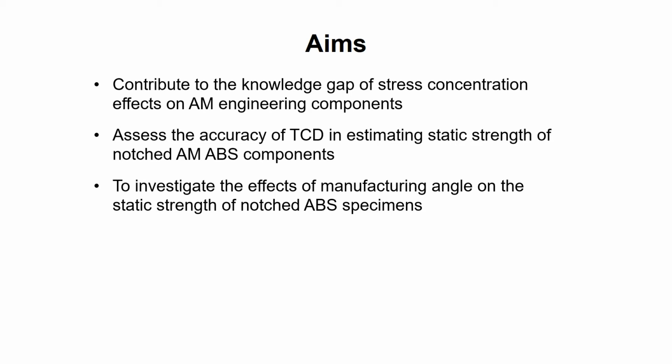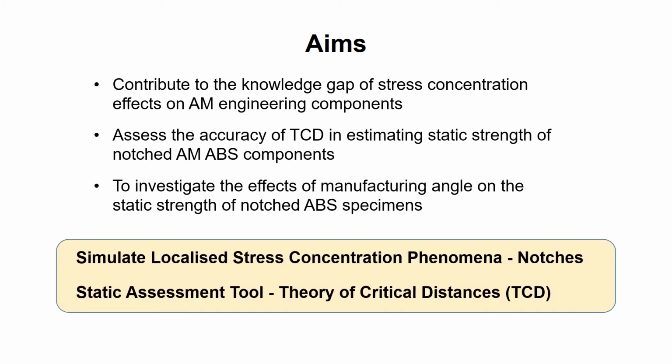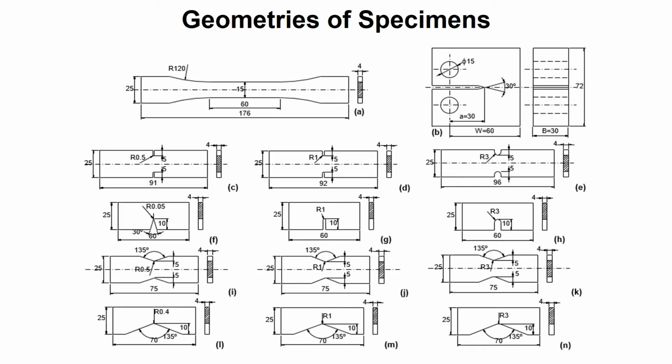So some of you may ask, why do we introduce notches in our experiment? The reason is to simulate the localized stress concentration phenomena by introducing notches on the AM components. Note that the static assessment tool that we are referring to here is TCD. The configuration of additively manufactured ABS specimens is as shown in the figures.